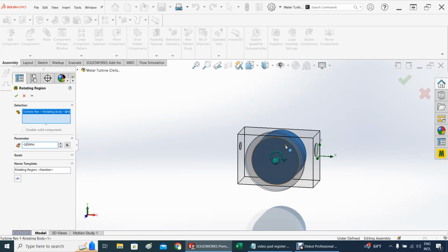For example, if you put 0 RPM here, that's the maximum amount of energy that you might extract, from this impeller not moving at all, because you are holding it in place, and that would be maximum torque. As you start to move, the torque will get smaller and smaller. You're going to get to a point, maybe 500 RPM or 600 RPM, where you are not extracting torque at all. It's moving kind of free spinning at the pressure drop that you get from this point to this point, and that's the torque that you're extracting multiplied by the RPM. And if torque is 0, obviously you are not extracting energy.